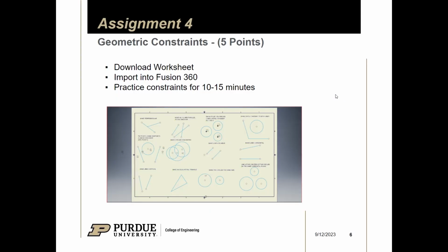So yeah, that's how you do constraints. It's pretty nice, and it's very powerful. Please utilize them. When I was first CADing, I didn't have any training, so I didn't know anything about the geometric constraints. I'd be setting things to 0 inches from each other, and it made things annoying because there was a lot of unnecessary stuff, and it would break my constraints and say it's over constrained. So don't set things to 0.